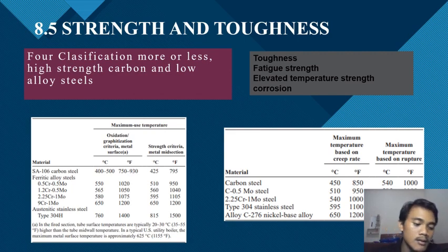The rate of creep deformation increases and becomes dominant when temperature approaches 0.5 Tm, where Tm is the melting point expressed in absolute temperature in K. The melting point of iron is 1813 K or 1540 degrees Celsius, so creep behavior of steel becomes more noticeable at approximately 700 K or 430 degrees Celsius.